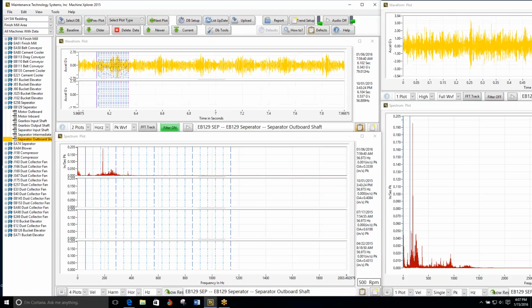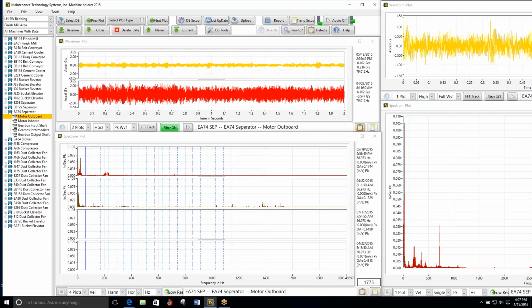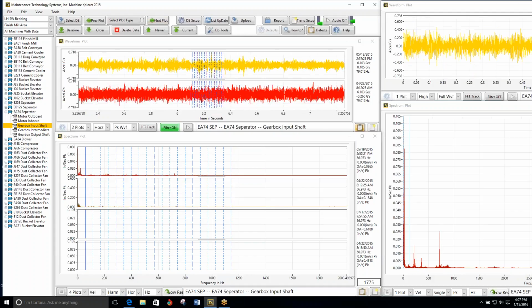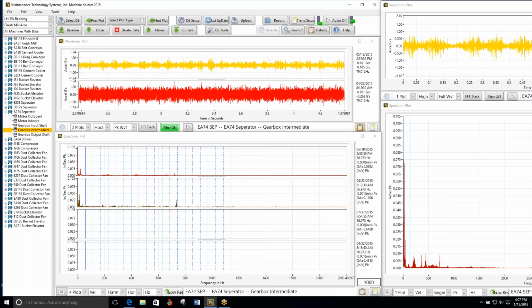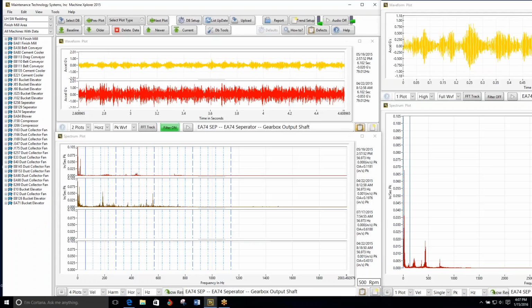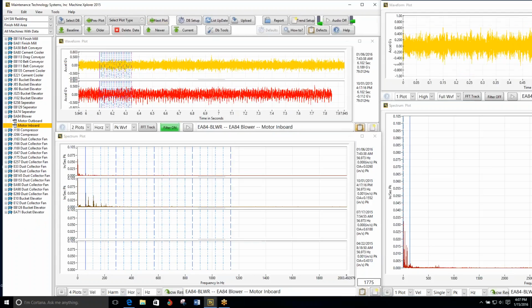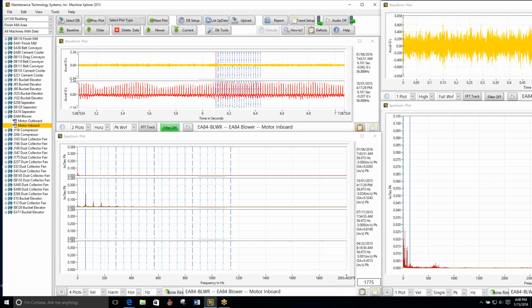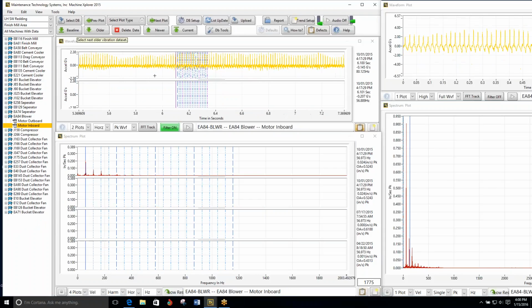And so I'm basically going through this by the amplitude and the waveform. As long as it stays below that 3 Gs, I just keep moving here. That's probably a really good way to do that. Otherwise, you'd spend too much time doing analysis. Look at that one, from back in October. Wonder what that one is. Let's pull him up here where he's the top one.